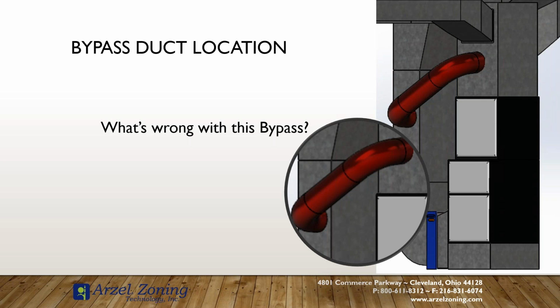It's going to be the most common installation, but it's a bad place for it, because it's got too many turns, which are going to reduce its capability. So your plenum is a mixing pot, but that's also going to be the most intense for your BTUs, and your return drop is so close to the furnace that there's no real tempering of those BTUs. So you're taking the hottest part of your furnace and you're dumping it directly back into the furnace without any means of tempering it to bring it to a more reasonable temperature.